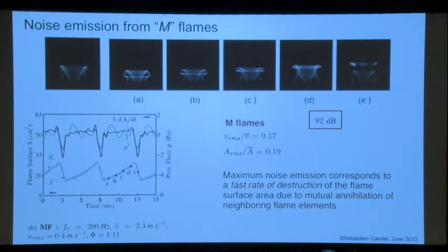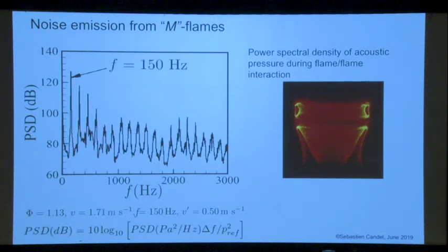Of course, you have to take into account the delay. You have to shift the pressure waveform to compare it to dA/dt by a certain amount of delay. You take that into account. You know the delay. This is a much louder process here. You see, and basically it's the burning of this that provides the radiation. In this case, you have not only the main frequency, but a lot of harmonics. You see, the spectral density shows you many harmonics.